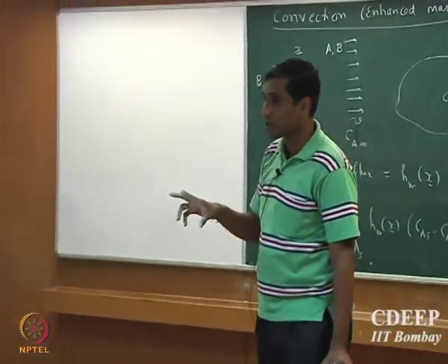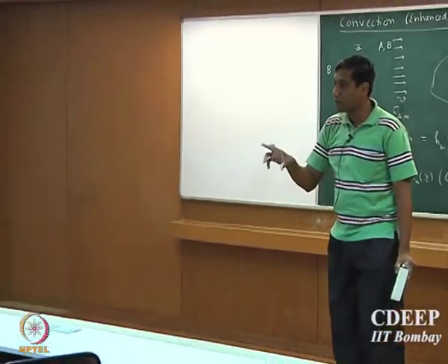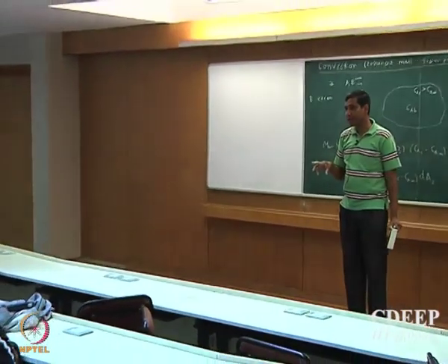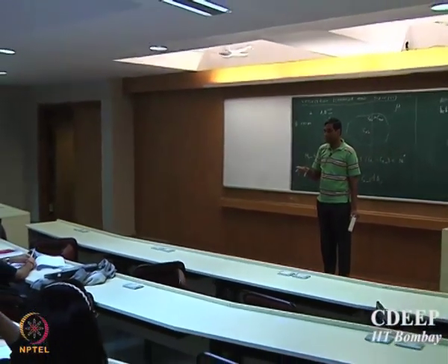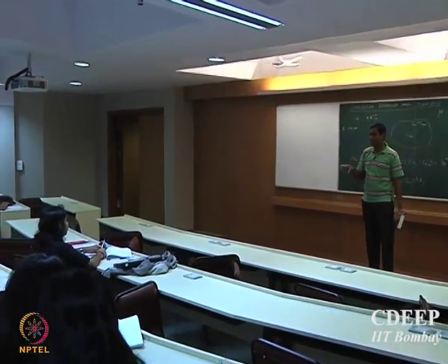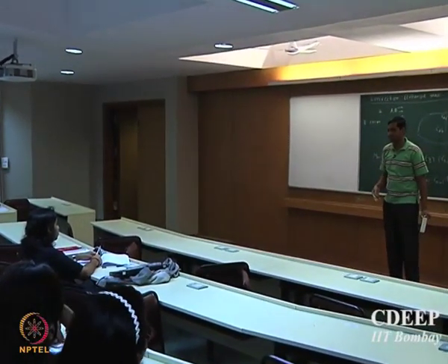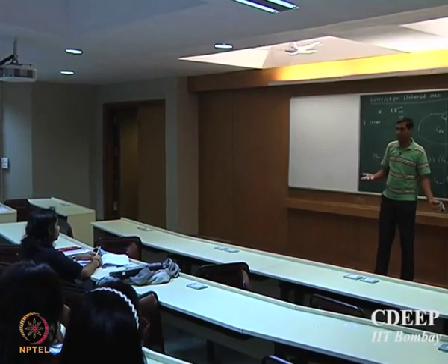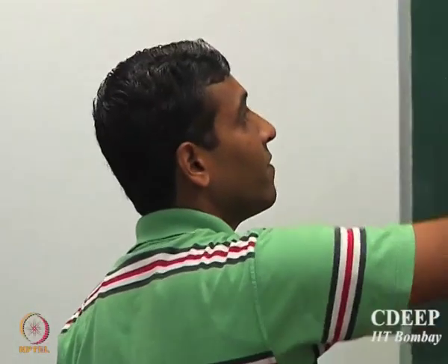It depends on the size of the system. Remember the lumped capacitance method we talked about: if you can maintain your dimensions such that you can maintain a uniform temperature and uniform concentration, why not? It's possible, very much possible. Okay, so similarly we can define what is called the average mass transport coefficient.